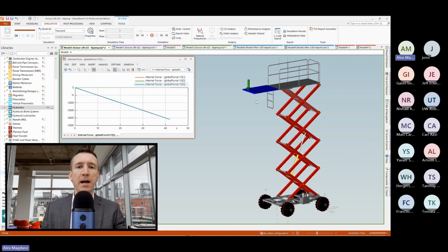Now you may think it's stupid to have the extension there, it should be on the other side, but I actually tried that first and didn't think about the fact that there's nothing holding the ladder side of that aerial platform down. The rollers hold it up, but if you added an extension on the other side for this particular design, the platform would flip over. Another benefit of simulation. So to keep things simple, we're just going to add the extension to the ladder side.